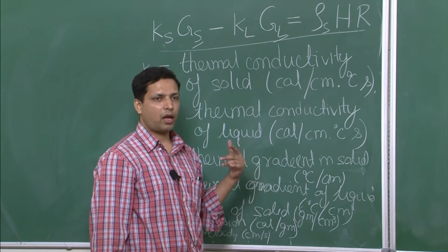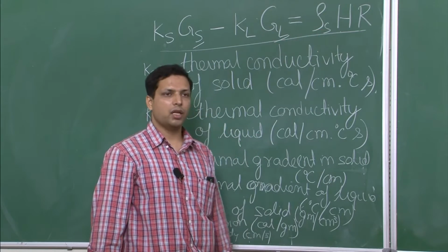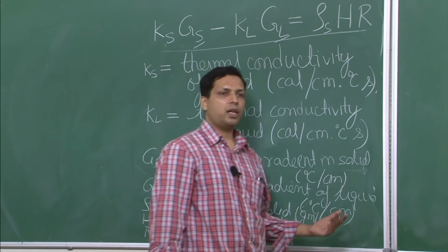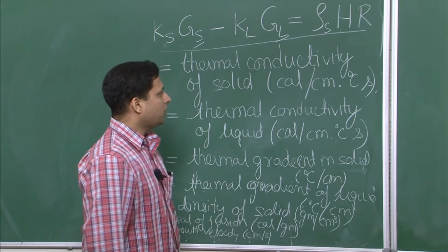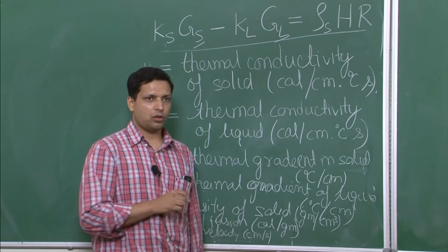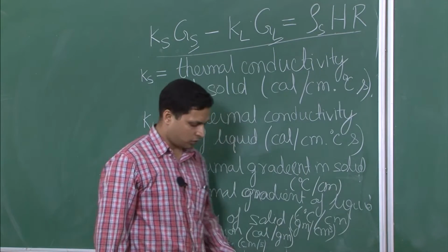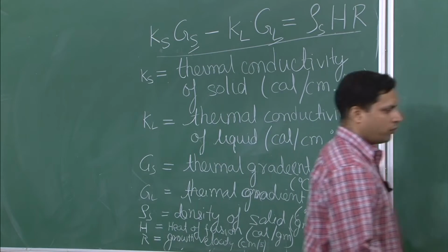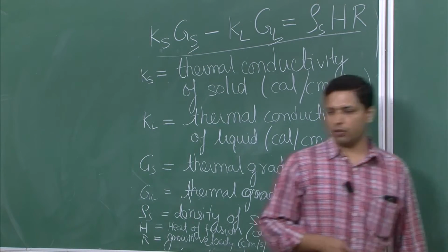But if you do it at a growth velocity higher than what is recommended by this equation, then what you get is not a single crystal. So, in order to get a single crystal, your growth velocity must be small and match the theoretical growth velocity. Now, when we say small, we still do not ideally want it to be very small.